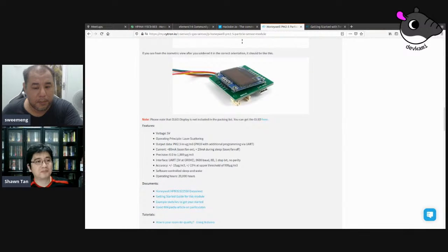So for example, if you wanted to emulate a UART, you need to know how the UART physical frame is supposed to look, the ones and zeros. You can use a GPIO to produce those frames or read those frames, either as an output or input.